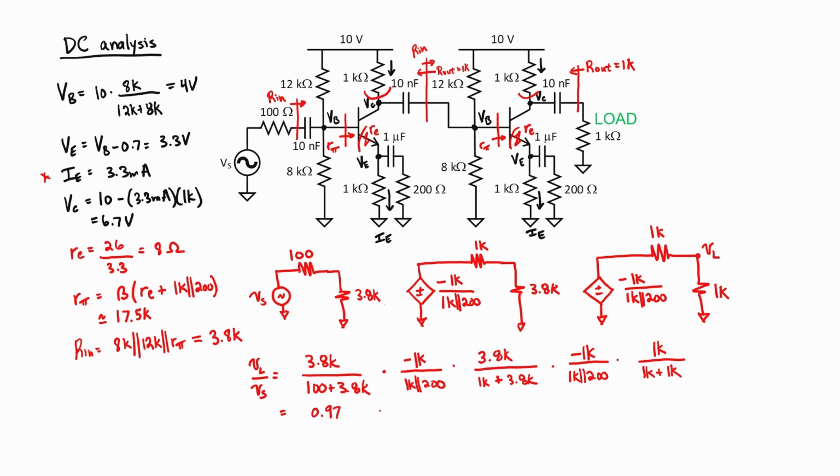We have a nice high input impedance, so we get a number very close to 1 there. Our gains are -6. We lose about 4/5 of our signal here between the amplifiers due to the resistors creating the bias network, and then we lose half of our signal here at the load. Overall, our gain is a positive 13.7.